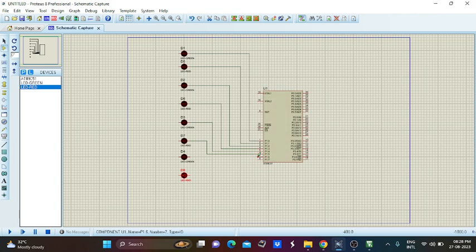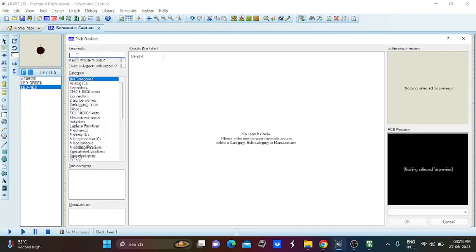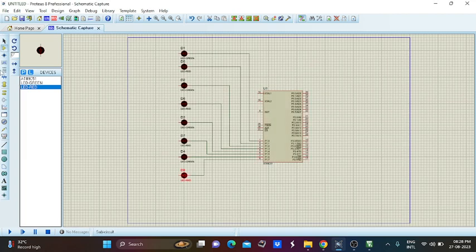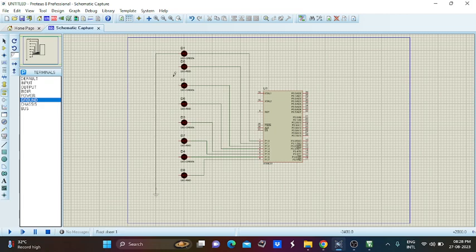We have to carefully connect this wire. If any dots or some other unwanted component is placed in between in this schematic area, the program will not run. So finally, after completing this process, we have to take ground. So go to this place, terminals mode is there. In this, we can select ground and place it here. After placing this ground, we just connect all those things. That is, the cathode terminals of all LEDs are connected here.